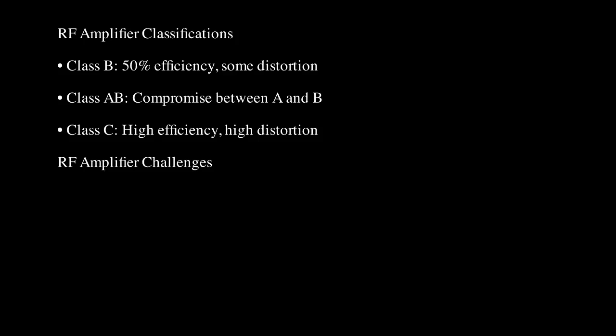Stability becomes difficult as frequency increases due to feedback through parasitic elements. Noise figure becomes critical in receiver front ends, where weak signals must be amplified without adding significant noise. Parasitic capacitances and inductances in transistors and circuit layouts limit bandwidth. As frequency increases, these parasitics become more significant, eventually limiting the maximum usable frequency.